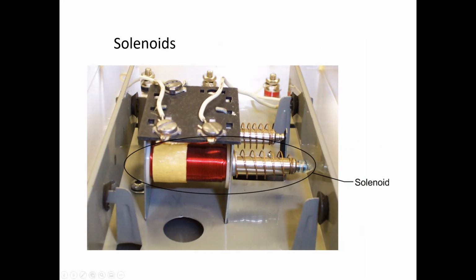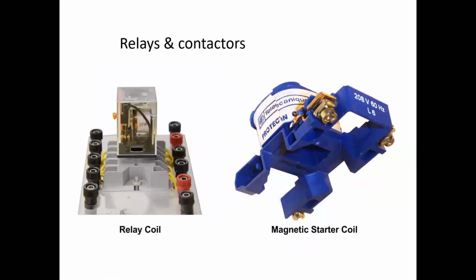Solenoids are another example of inductors in industry. A solenoid is identified by a movable solid core that moves with spring action back to its original place from its actuated location or position, which is due to electromagnetic flux from an electromagnetic coil. Solenoids are seen in doorbells as well as valves that are used to control fluids in piping systems. Relays and contactors also exhibit inductance. This is similar to a solenoid, however, the core remains in its fixed position and an armature moves, which opens and closes electrical contacts.